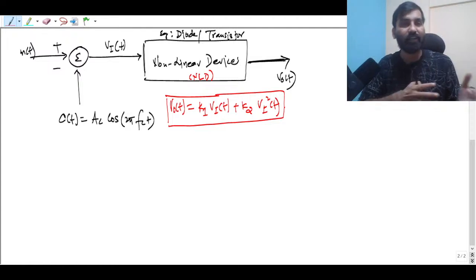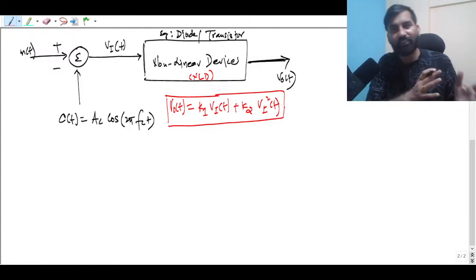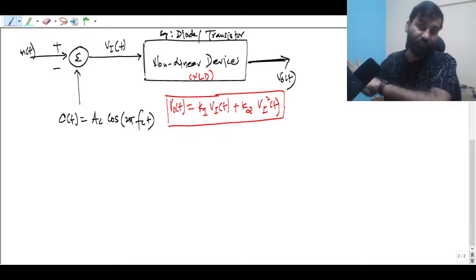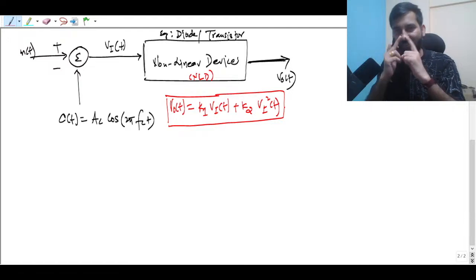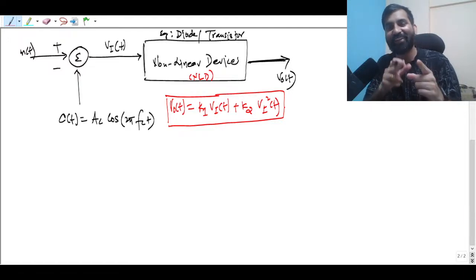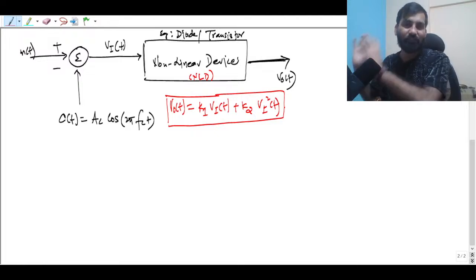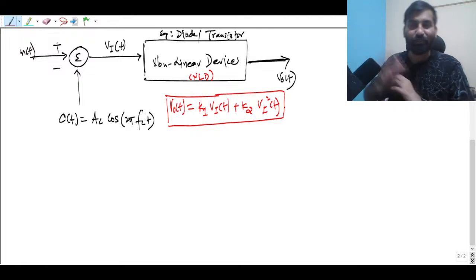In the receiver side, what you have to use, guys? In the receiver side, you have to use an ideal band pass filter. In the transmitter, not receiver side, please correct it. In the transmitter side, you have to use an ideal band pass filter. In the receiver side, you have to use a low pass filter.